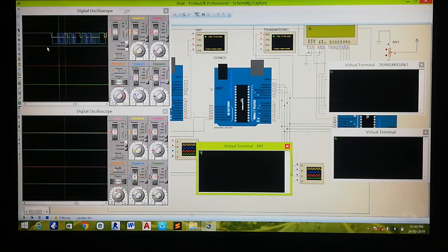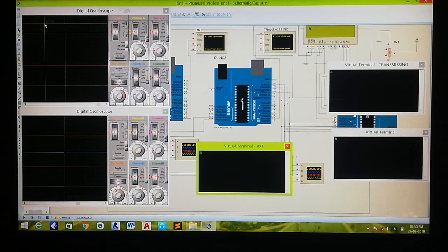Okay, that's it. This is the SPI protocol. You can ask where is the I2C. So sorry, this is an I2C protocol where the start bit takes place, the address takes place, and then another read/write status, followed by data, and then the stop bit. This is all the requirements of an I2C data package.